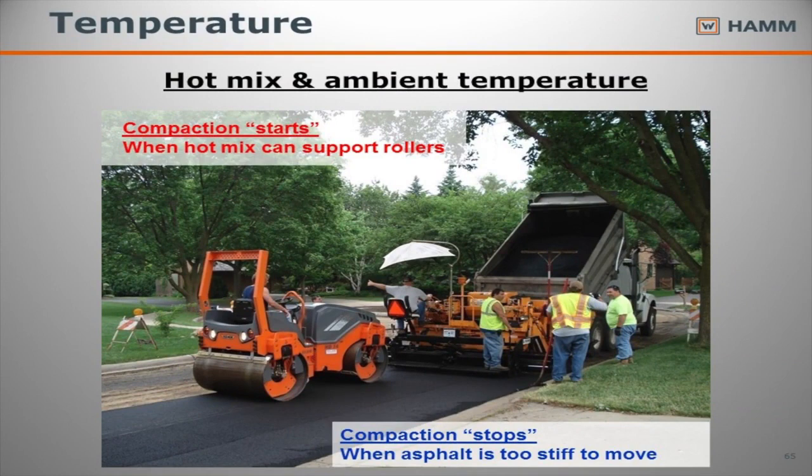One of the other things we look at when we look at different projects is we want to make sure we have the right size roller for the project. If I'm doing a small cul-de-sac area or city street, I want to have something that has maneuverability, but still has the compaction force of getting the compaction I need with the material I'm doing. I don't want to have a big 84-inch wide, 14 ton roller trying to get around here. I'm just going to tear that mix up and it's going to look terrible. So understanding where you're going and what you need to do, have the proper roller for what you do. Sometimes you don't have control over that. I know contractors, they just ship stuff out. This is what you're dealing with. But they know they're not going to put a big roller in a small project like this.